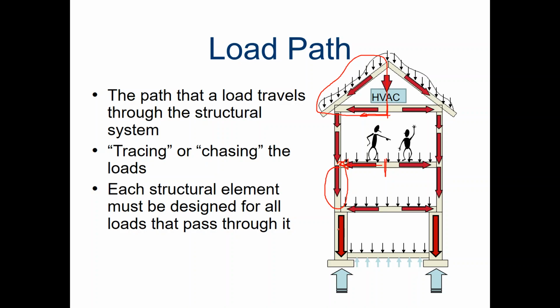So if you notice, this bottom column here is a lot thicker. If you could imagine this building maybe 10 stories high or something, imagine all of the weight that the lowest columns would have to be supporting. So all of these arrows are showing us how these loads are chased through. We get down to the main level here, and we have this much thicker column holding everything above it.